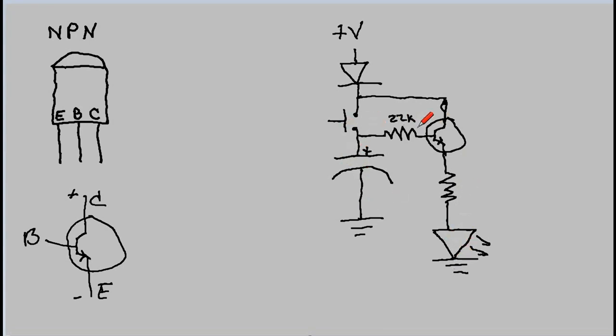In this instance, it takes very little voltage to keep the switch on, and the capacitor is not powering the LED. Well, theoretically, I'll explain that a little more in a minute. But the capacitor is not powering the LED, but just turning on the voltage to the switch. So it needs very little voltage, which is why we have a 22K resistor. And a common resistor for an LED is a 470 if we're using 9 volts. So let's assume it's 9 volts.